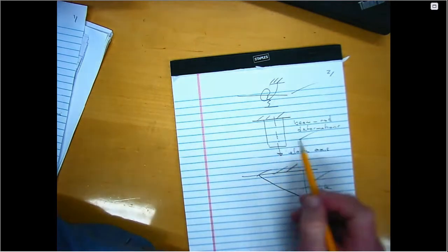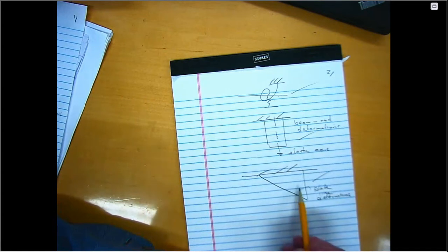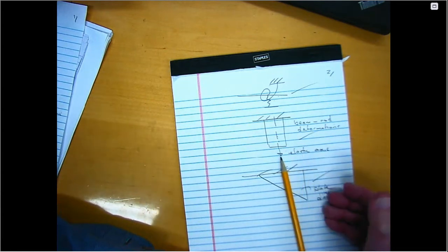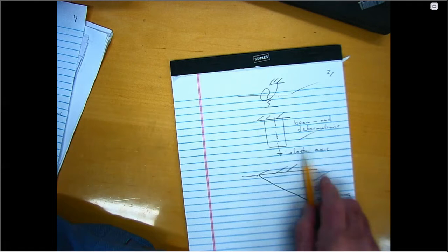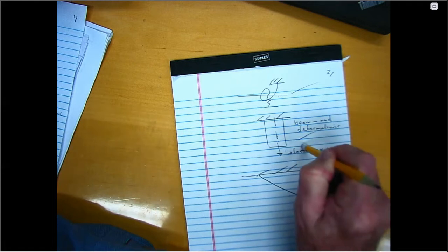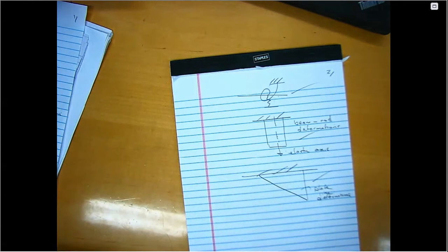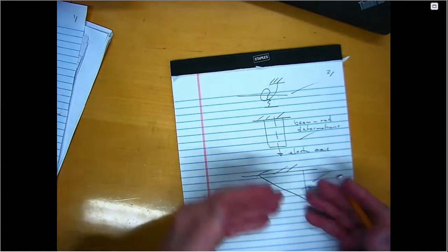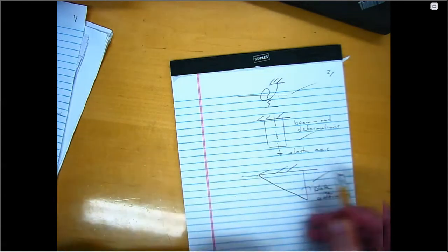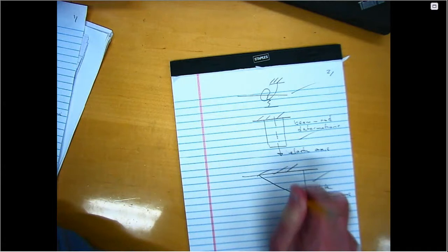In this case, if there were an elastic axis, I could start out with a plate-like model, but it would reduce to this model. But usually, since someone is designing a wing or airplane, they know whether they're going to build it so that it has beam or rod-like structural characteristics or plate-like structural characteristics. This is typical of low-speed aircraft. This is high-speed.